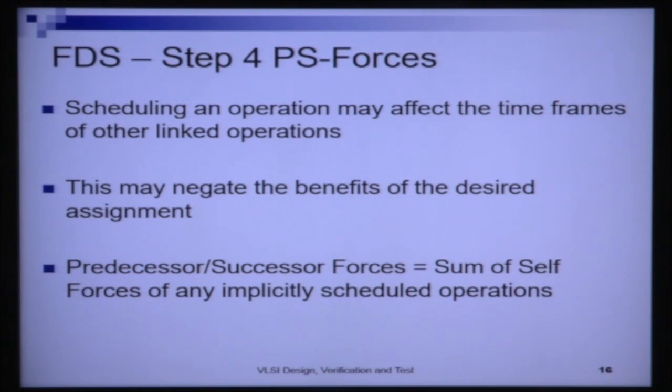So, if we consider only self forces, we could do the scheduling based only on self forces. What would that do? It would find the self force of each candidate operation, each ready to schedule operation at a given time, and then it would take the one with the least self force and schedule it.